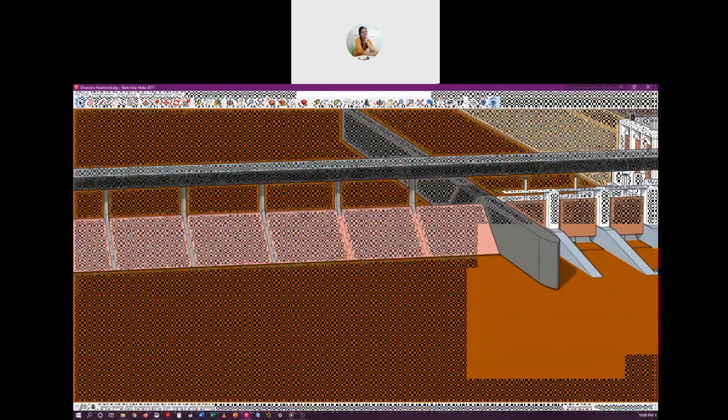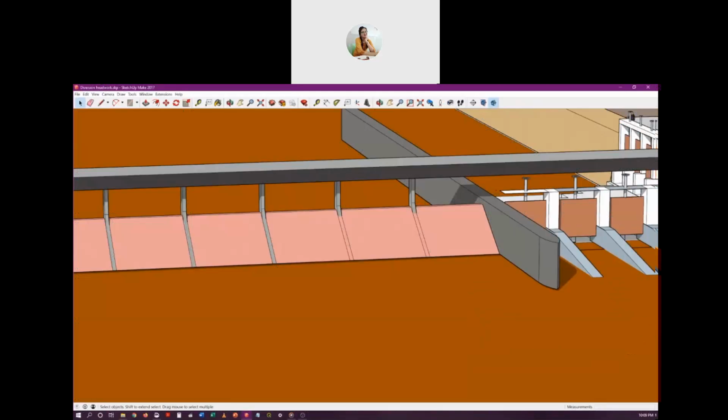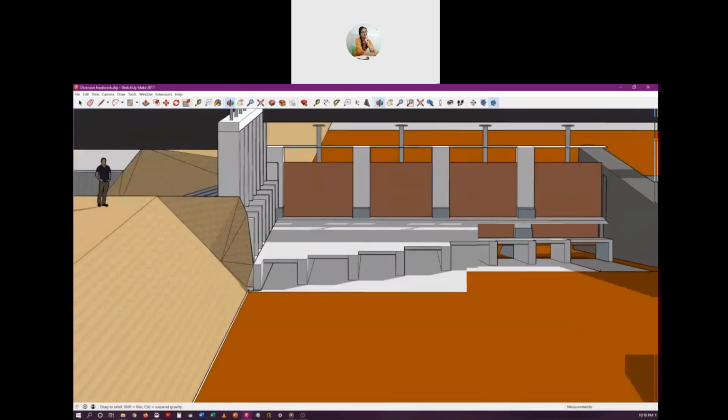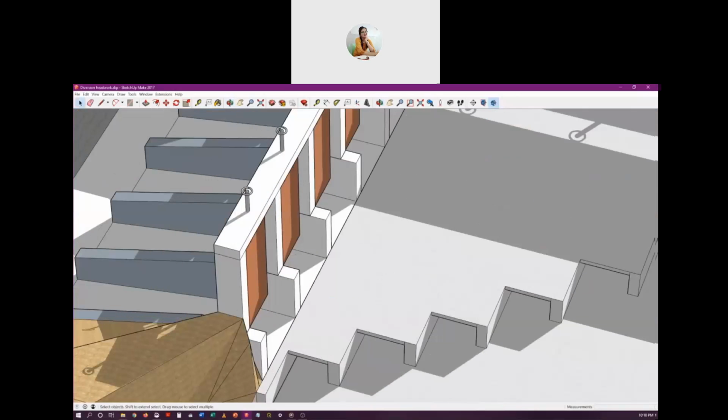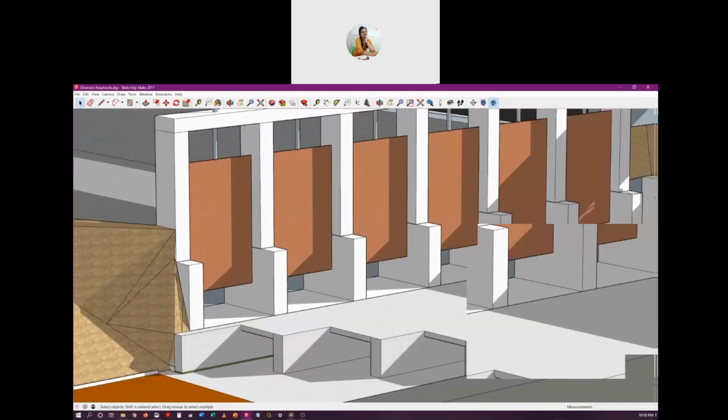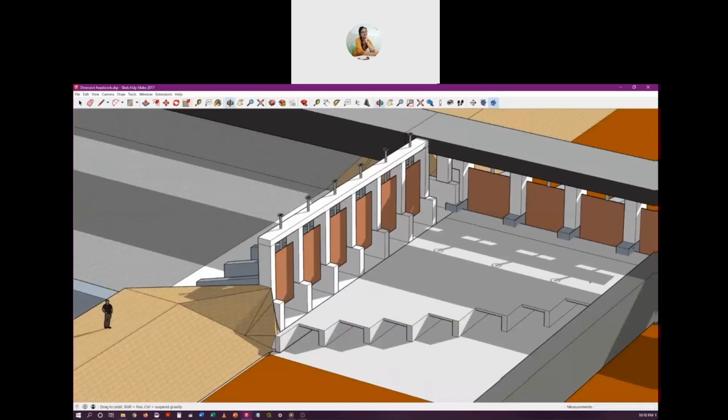Now, let's discuss some more about these undersluice, the silt excluders. See, they have a very peculiar arrangement. These are long tunnels. The tunnel very close to this head regulator, through which water is transferred to the canal, is the longest, and as we move away from that, these tunnels become shorter and shorter.